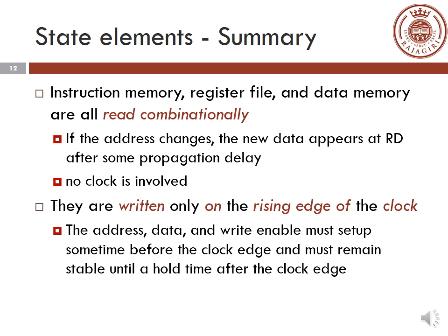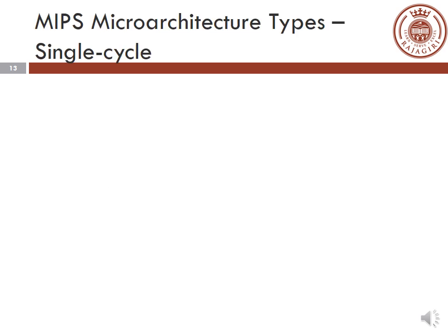So write operation is sequential, whereas read operation is combinational. There is no clock involved in your read operations, and you have a clock coming into the picture in your write operations. So we have concluded the state elements.